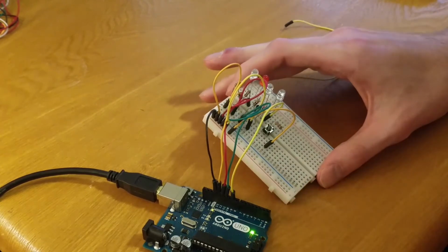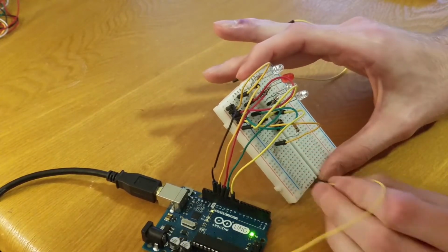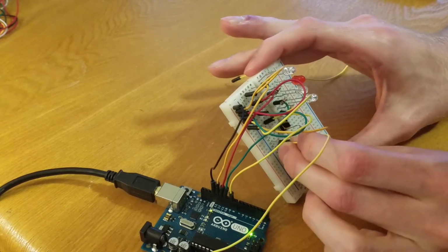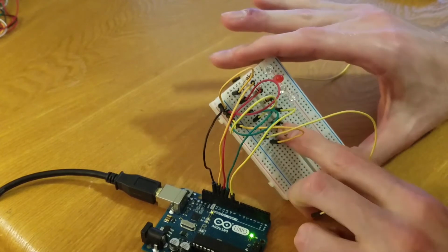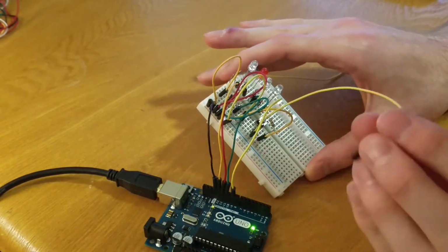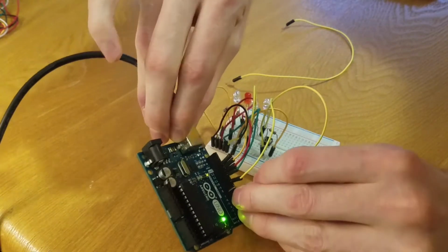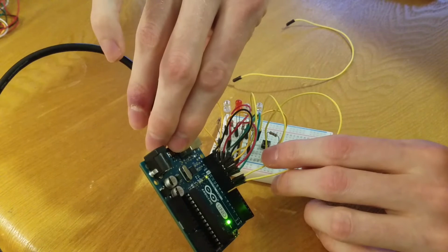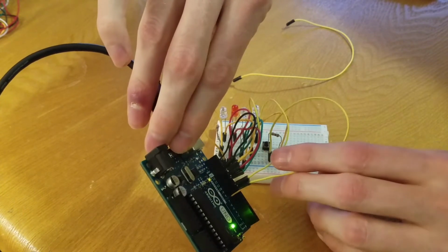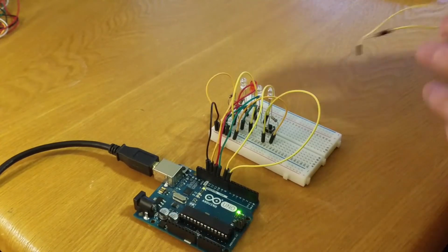Okay, we also need a digital pin for the button. So that's going to go on line 15. The bottom line of my button. And then the other side is going to go to pin 8. There we go. So my 2 yellows, I know that's my button press. Those are on 9 and 8. 9 is the bulb, 8 is the button. We'll need to know that later.